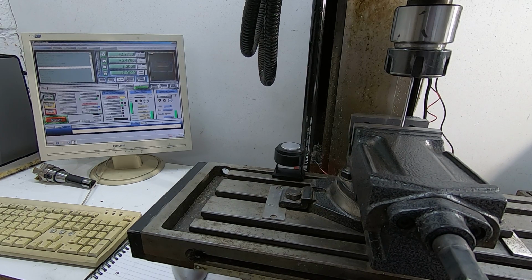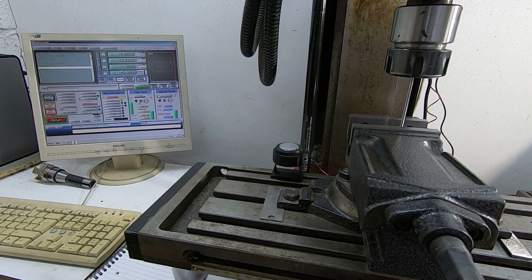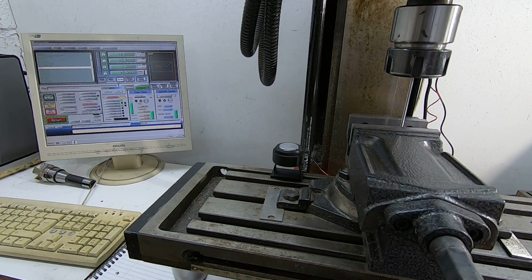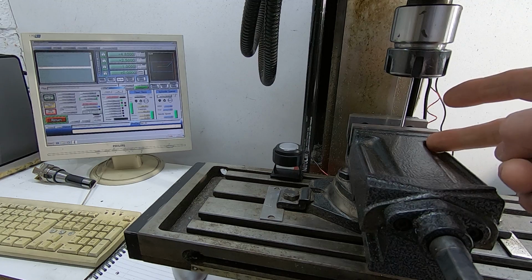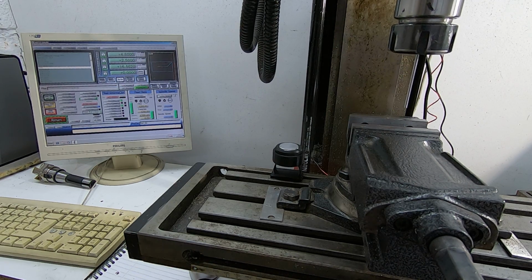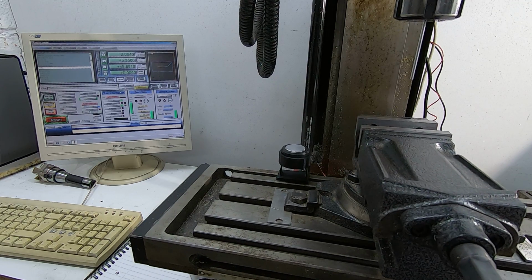So the milling operation is underway. This would normally be machining away the material, and at some point we'll get this. It's found a tool change request. This is just what I've just inserted for test purposes. So we can either click cancel, in which case it will just carry on milling, or we can click OK, in which case it will do an actual tool change. So I'm going to click OK so we can see the two macros working. So first it will start by running the M6 start macro. So it's going up to the Z safe location.